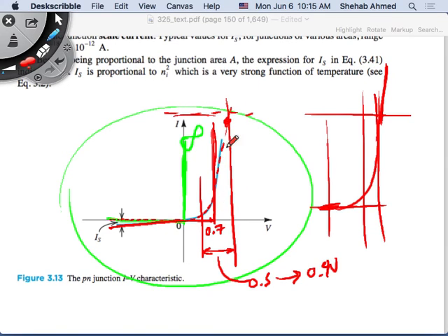Because you have a voltage and you have a current flowing. Voltage times current is power. Power is limited by the power dissipation. That's why they tell you it's always within a range, because it's limited by the power dissipation of the diode. Okay? So we have three models now: ideal, piecewise linear with a forward voltage taken into consideration, and then the exponential.